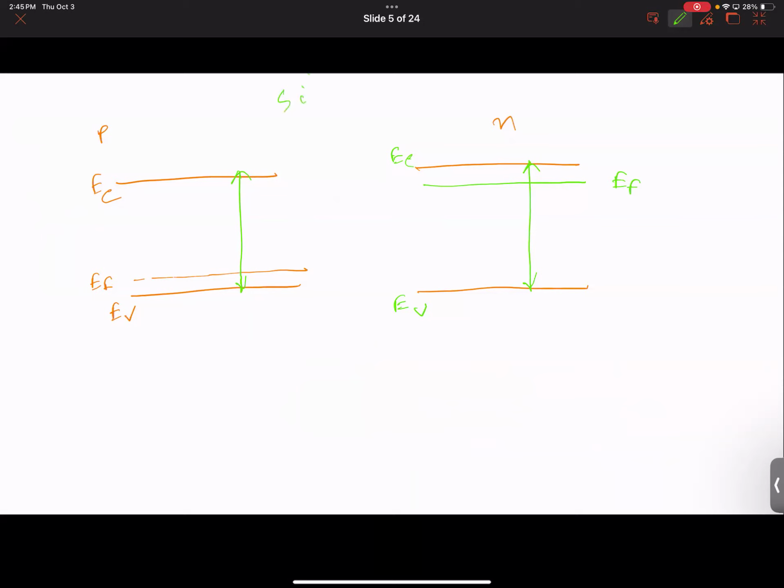As long as you're dealing with the same material, the band gap is a signature of that material. Remember, there will be heterojunction devices at some point, and the name tells you there will be different types of materials, N-type silicon, P-type germanium. Imagine that, right? Then this concept will no longer work. There is a chapter on heterojunction devices, by the way, and I think I'll cover it a little bit in this course as well. So hopefully, if you understand this well, you'll see the difference.